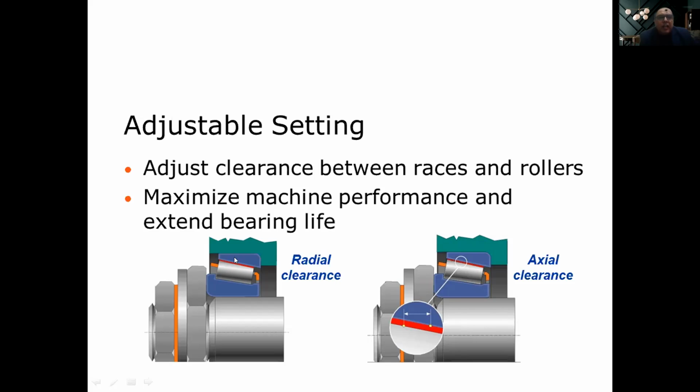So it is a negative clearance. That means the surfaces are pushing into each other. So it will again depend on the application: what the system stiffness and rigidity are, what the speed is, what the load coming is. The designer will calculate the play in the system.